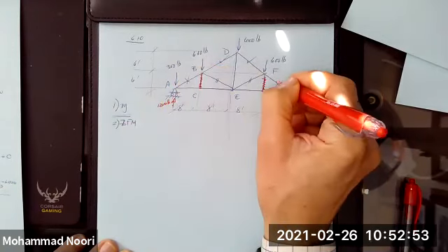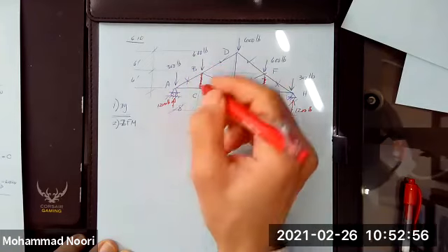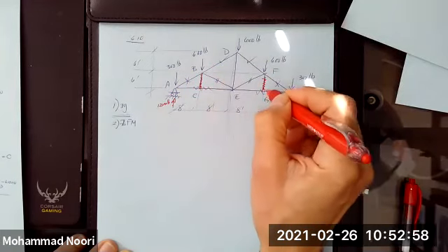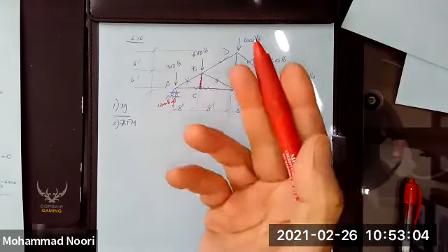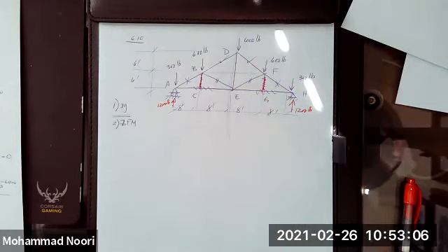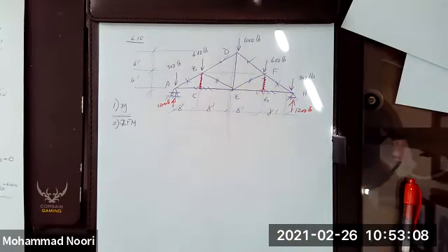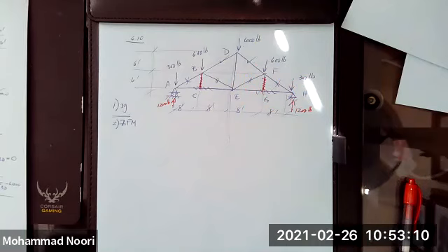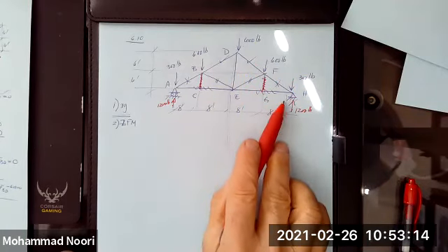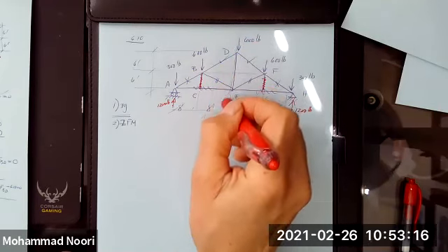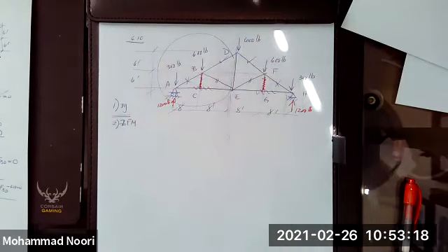Forces in these 2 members would be the same. Forces in these 2 members would be the same. So you don't have to use every single joint to find these unknown forces. All you do is basically do half the truss, and that's what I would do.